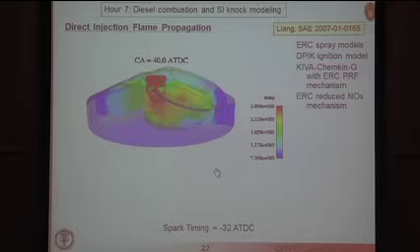What I'm showing you here, this black line, is the G surface that we discussed. That is for the propagating flame. Now the flame is propagating through a mixture with varying equivalence ratio that is established by that spray. Here's our spark plug, and here you see those spark kernels, the DPIC ignition model, and some details of the models here.